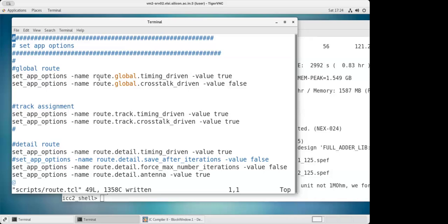If it is green, it will route. It will assign, okay, I will route this wire from this particular place. That is the first stage. If it is red, it will search for another place: I will not route from here, I will route from here. So there is something known as a color map. It will tell you, I'm not able to route from this particular area because there is a lot of traffic there. That comes as a part of